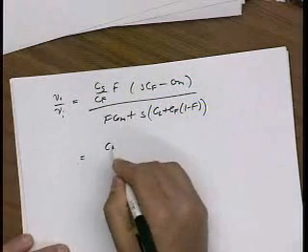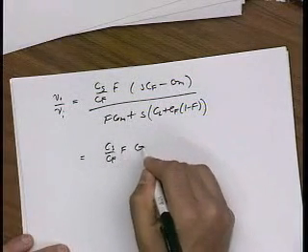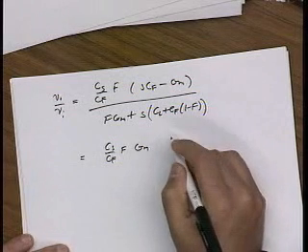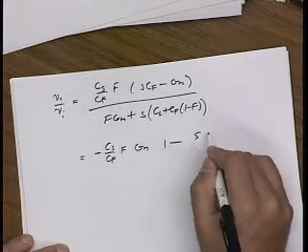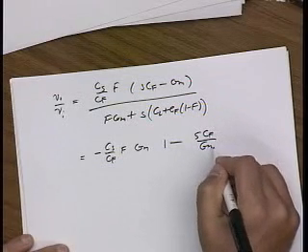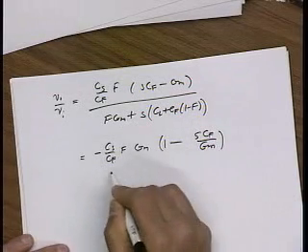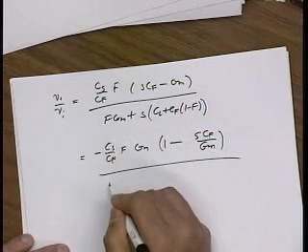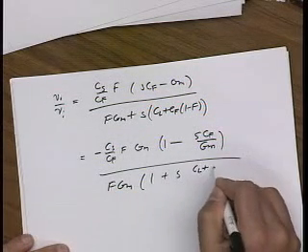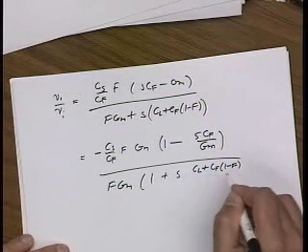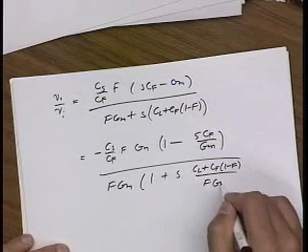Well, let me factor out a GM from the numerator, and put a negative sign here, so I'd have 1 minus sCF over GM. On the denominator, I'm going to factor out an FGM. So this is 1 plus s(CL plus CF)(1 minus F) over FGM.